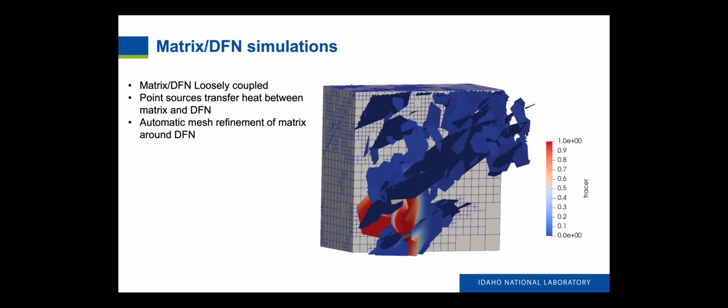Later on, we do intend to have these fractures more active, looking at things like XFEM or maybe an IPG formulation, or some cohesive zone modeling for damage, or also a phase field. So we're still looking towards some of those. For right now, we're just trying to keep it simple, because when we add more physics to these things, the computational time becomes somewhat intense. And so we're trying to get some quick answers for right now to help inform the planning.